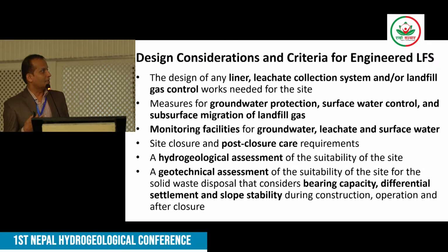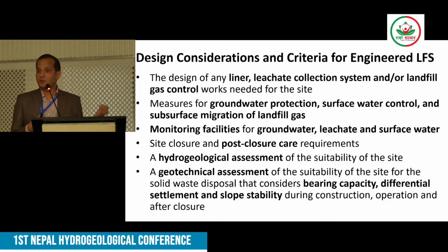And of course, there should be groundwater protection work as well as surface water control and control of subsurface migration of the landfill gas. Methane is one of the major gases we generate in the landfill site. And of course, the monitoring of the groundwater and leachate. Because we should have some groundwater monitoring wells on both the upstream and downstream sides. And most of these monitoring wells are missing even in the sanitary landfill sites we have developed.